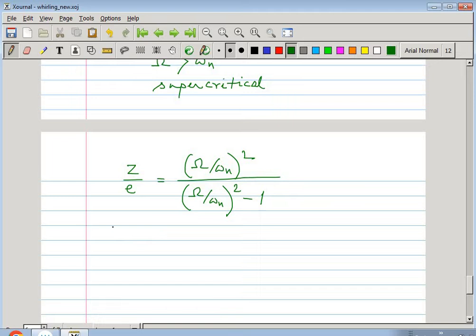And you are given mE. So mE is 0.02879 kg meter. m is the mass of the rotor, so mass of the disc, 13.6 kg. So from here you find out e, and e is 0.0000211 meter.